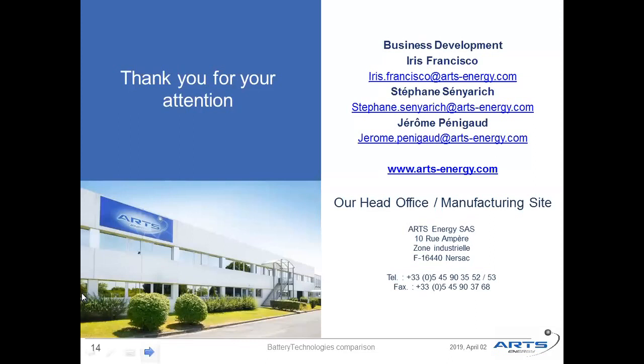In iron phosphate or standard lithium, the electrochemistry inside makes some particles, and so in that case, it's not possible for safety reasons to charge. As I said during the presentation, it is not a question of chargeability or a question of performance. If you charge a battery below 0, you can charge it. It's possible, the battery will accept. But there is a safety risk associated too. And this is why it is forbidden.